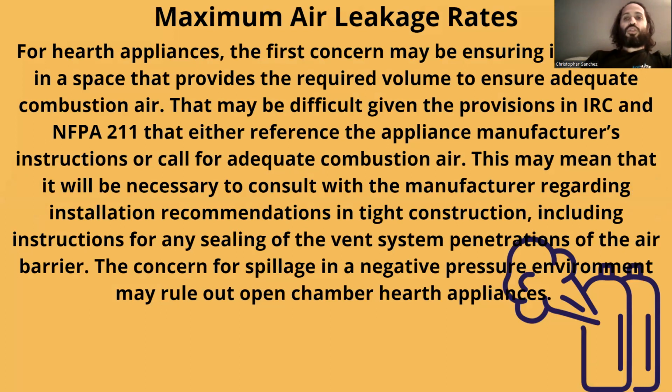For hearth appliances, the first concern may be ensuring installation in a space that provides the required volume to ensure adequate combustion air. That may be difficult given the provisions in IRC and NFPA 211 that either reference the appliance manufacturer's instructions or call for adequate combustion air. This may mean that it will be necessary to consult with the manufacturer regarding installation recommendations in tight construction, including instructions for any sealing of the vent system penetrations of the air barrier. The concern for spillage in a negative pressure environment may rule out open chamber hearth appliances.